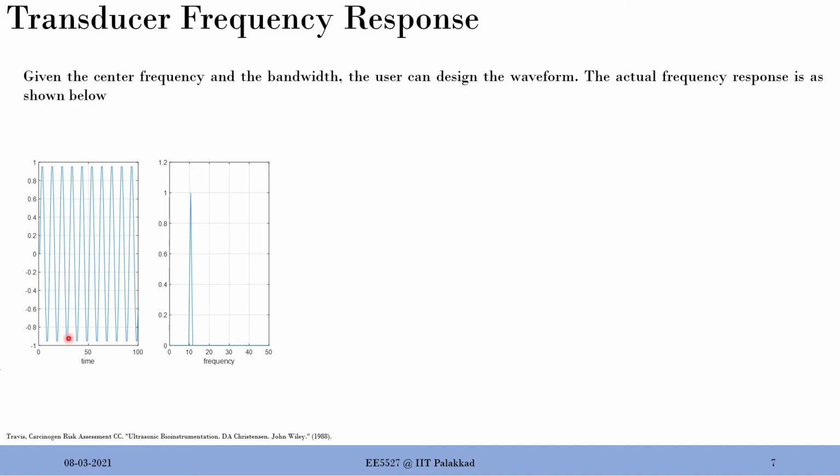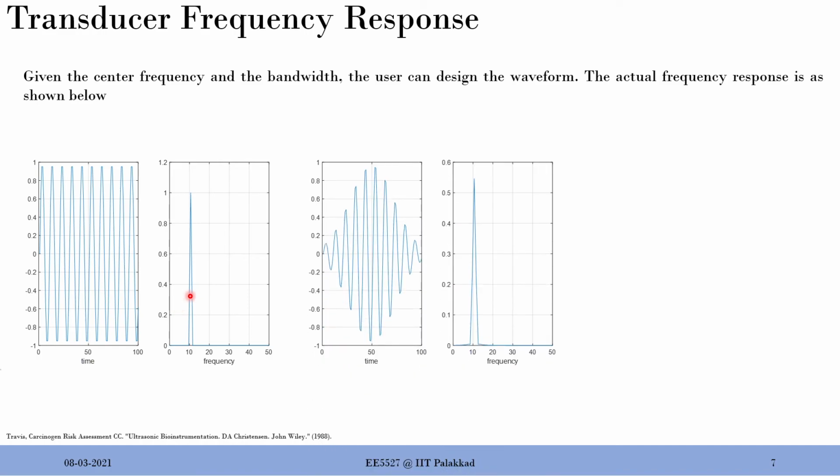I won't extend it to all 100 samples or 100 seconds in time. I am going to dampen it. This is exactly what happens when you have a matching layer and a backing layer in your transducer. This waveform will not be extending, it will get damped. So this is in time, and it gets damped symmetrically.